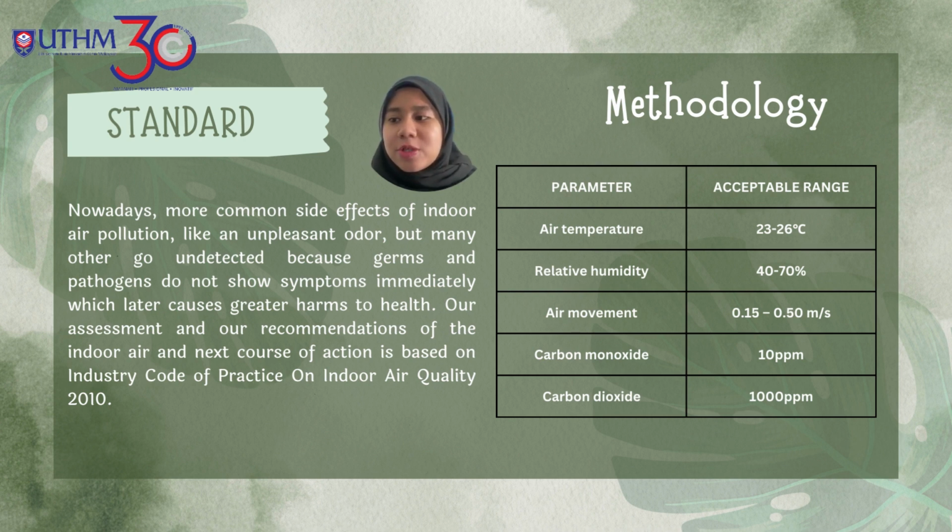Parameter for air temperature: the acceptable range is 23 until 26 degrees. For relative humidity, 40 until 70%. For air movement, 0.15 until 0.50 meters per second. For carbon monoxide, 10 ppm. For carbon dioxide, 1000 ppm.